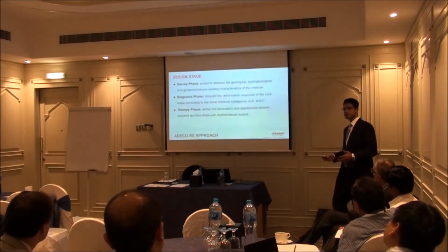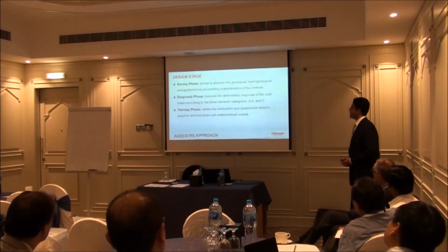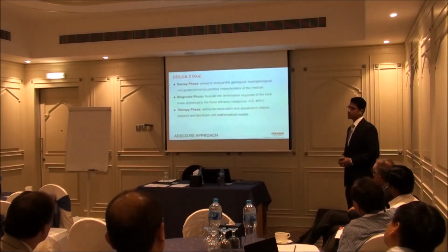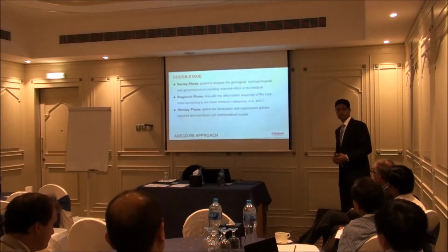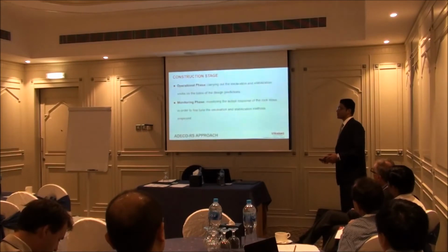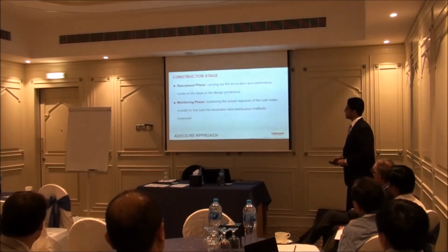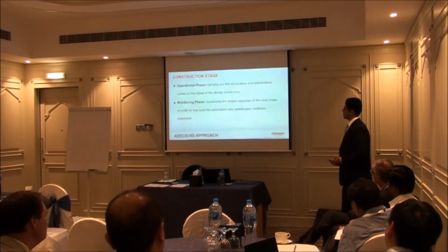So what is the survey phase? The survey phase is where the design engineer will survey and find out all the geological, geomechanical, or hydrological conditions of the rock mass. And the diagnosis phase will be where the design engineer will categorize what type of material it is according to the behavior categories. The therapy phase will be where they will prescribe what type of interventions or stabilization measures are required. The operational phase will now be where these findings are put to use, and it will start with the construction of the tunnel. The monitoring phase will be where all of these measures are monitored, and then maybe for fine-tuning the design, they will revisit the design.